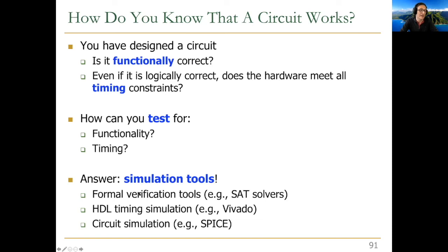Or you could formally verify a circuit. This is especially true for functionality. Timing is much harder, but you could use, for example, satisfiability testing solvers, SAT solvers, in other words, or other similar formal verification tools, to formally verify that your circuit actually does what it is intended to do. And we're not going to talk about that. Also, again, if you take a formal verification class, they may cover hardware design, because some of these formal verification tools are applied to hardware also. But in this class, we're going to talk about simulation tools quite a bit.